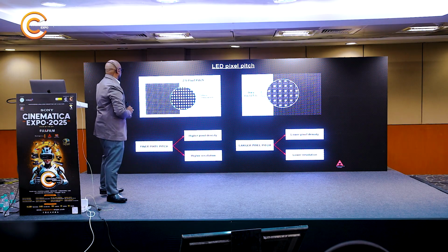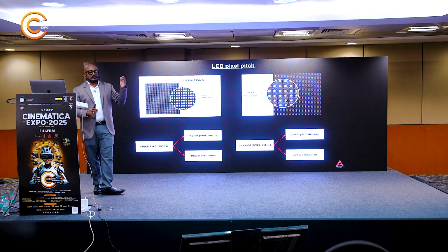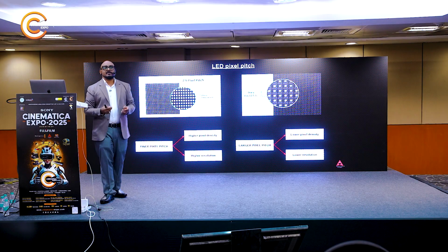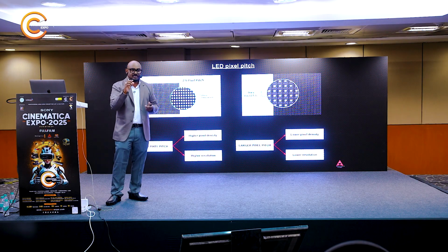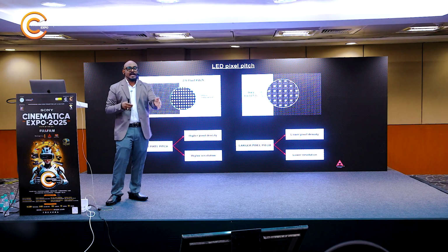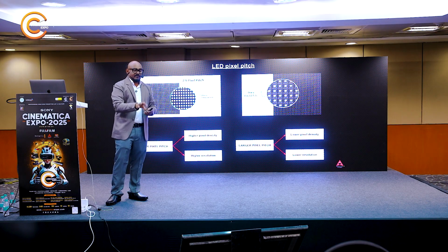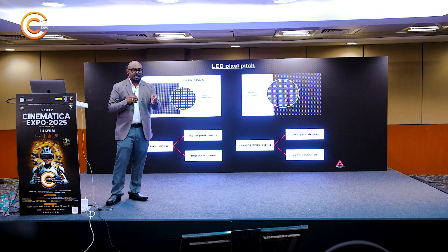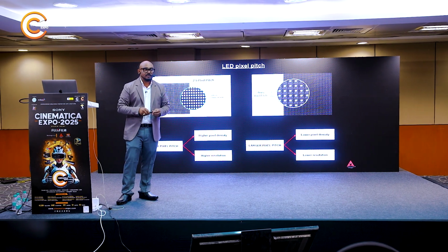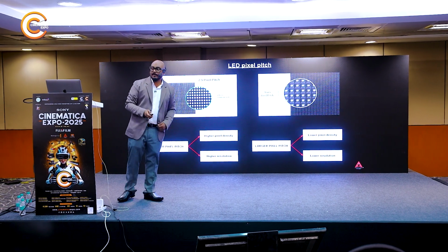So the finer pixel pitch gives you higher pixel density, which means that since the distance is less, you will have more pixels in the cabinet. So obviously you will have the highest resolution. In the same way, with a larger pixel pitch you will have fewer pixels and lower resolution. So that's a small brief about pixel pitch.